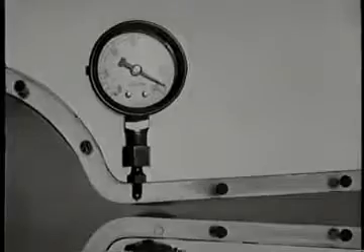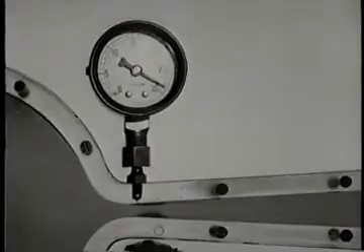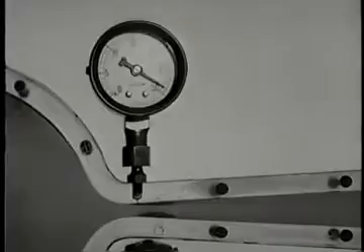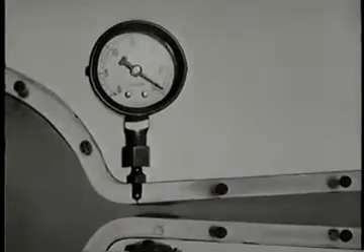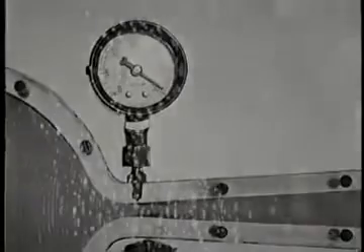When the absolute pressure goes below the vapor pressure of about 1 inch of mercury, boiling occurs. The water changes to steam, and the subsequent collapse of the bubbles, which you can hear, creates enormous stresses in the wall. Mechanical stresses owing to the implosive collapse of cavitation bubbles on a surface do great damage to hydraulic machinery. And to marine propellers.